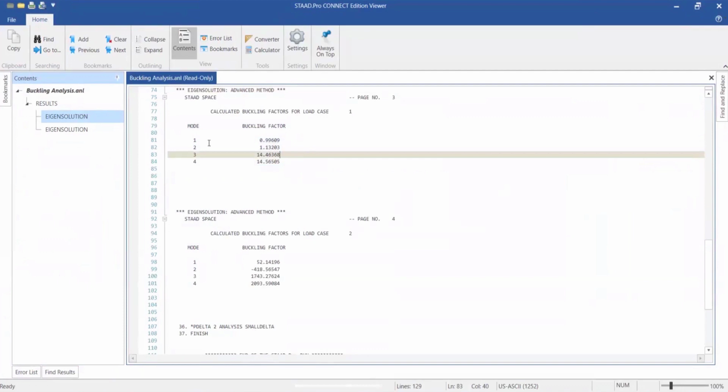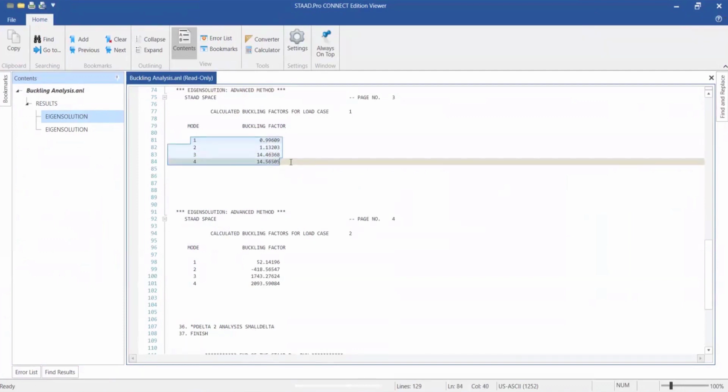Here I can see the modes, and I can generate modes. I think that was covered by Sudeep in the first session: that we can do a rigorous analysis, the advanced buckling analysis, using STAAD.Pro Advanced, rather than just doing the first mode by devising the stiffness matrix. So it's a better approach to do the buckling analysis as far as STAAD Advanced is concerned.